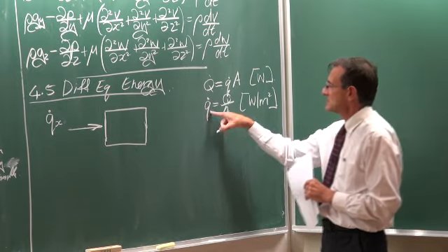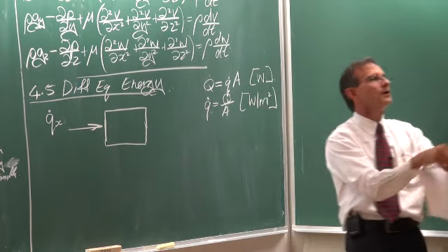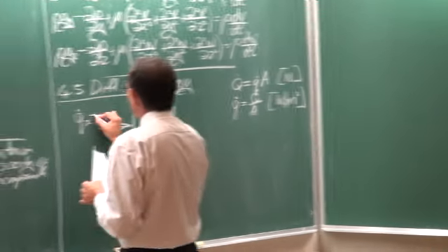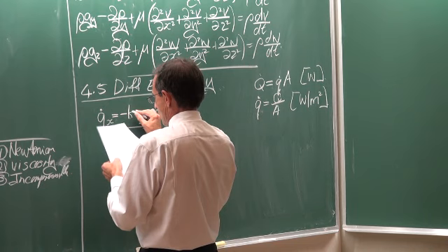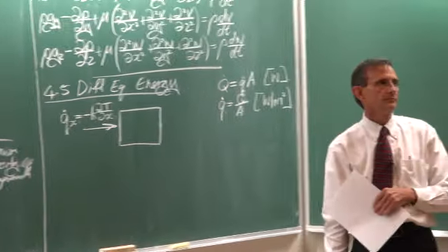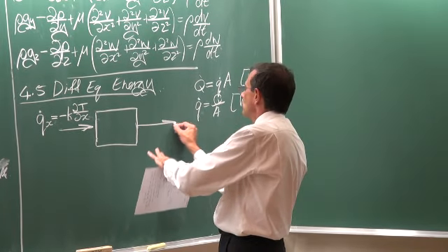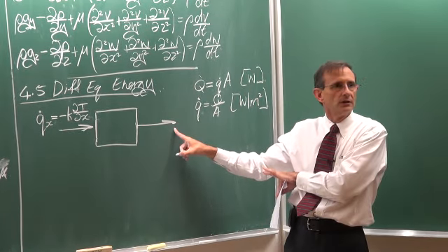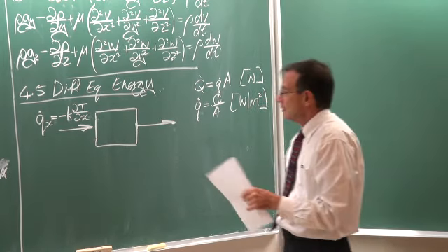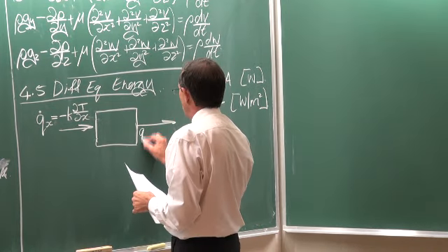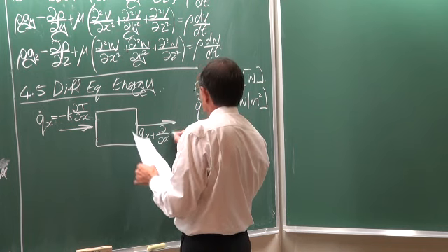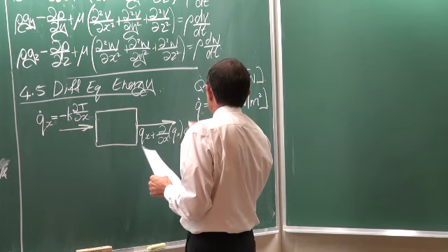So the heat flux is just the heat transfer per square meter. Okay. And that would be equal to, we know it, minus k multiplied by partial dT dx. Okay. The same thing now we do on this side. Again, use the differential approach. We would now say this is equal to qx plus partial d dx of qx times dx.